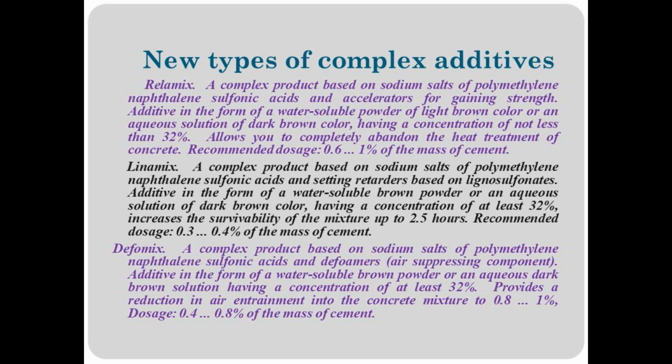Defoamix. A complex product based on sodium salts of polymethylene naphthalene sulfonic acids and defoamers, an air suppressing component. Additive in the form of a water-soluble brown powder or an aqueous dark brown solution having a concentration of at least 32%.